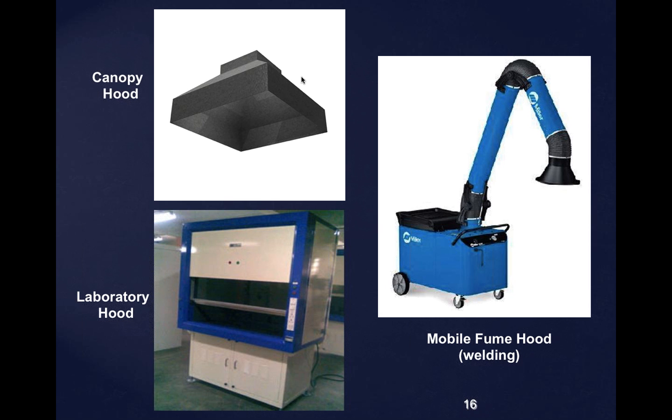Now, in the system we have downstairs, there is a blast gate. It's there so that as we do experiments, we can control the amount of air that we're pulling through, so we can do experiments with high flow rates and lower flow rates and so on. But in a real exhaust system, we want to avoid them as much as possible. If we don't mind the cost of energy, or don't want to spend a lot of time designing a system, we can install blast gates and just oversize the fan and the ductwork and everything else, and then just control it with a blast gate.